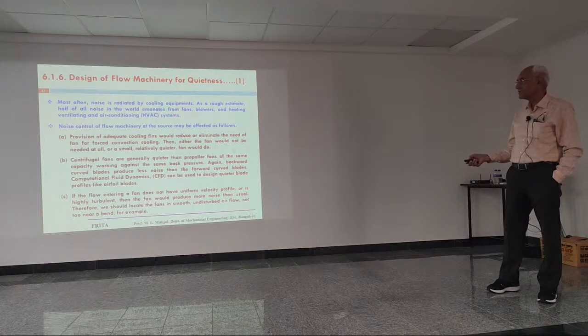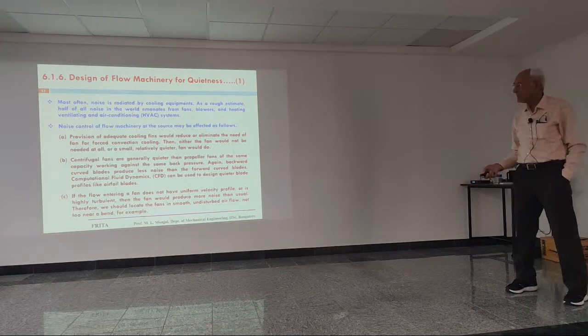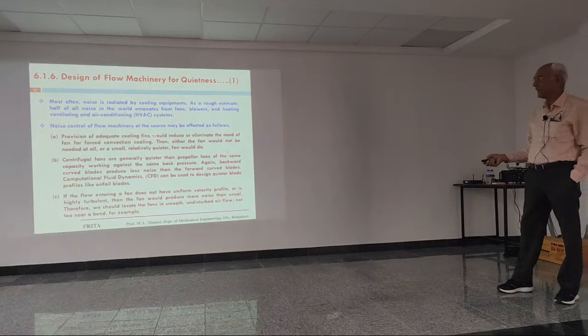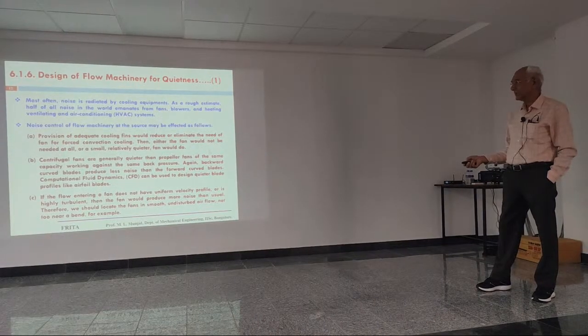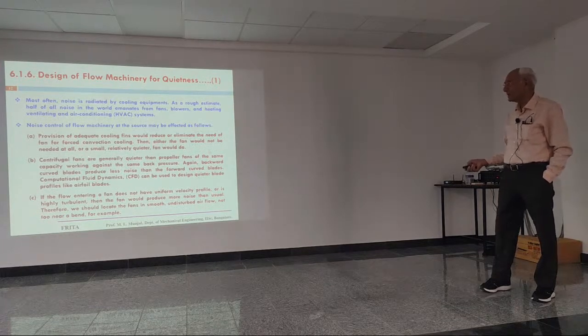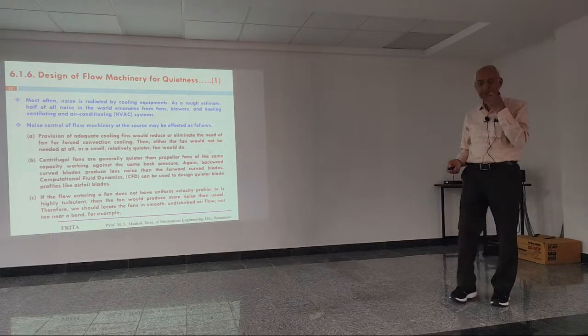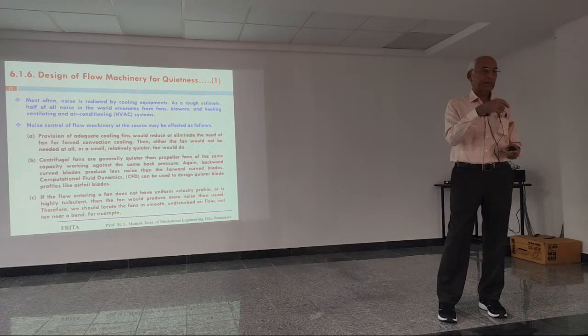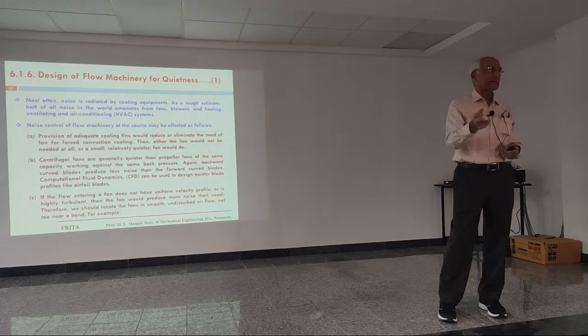Noise control of flow machinery at the source may be evaluated as follows. I am giving you various things. A. Provision of adequate cooling fins would reduce or eliminate the need for a fan for forced convection cooling. Then either the fan would not be needed at all, or a small, relatively quieter fan would do. What I am trying to say is that noise is being produced by the flow, but the flow itself can be reduced if the heat transfer coefficient has been increased by using fins rather than flat radiating surfaces.